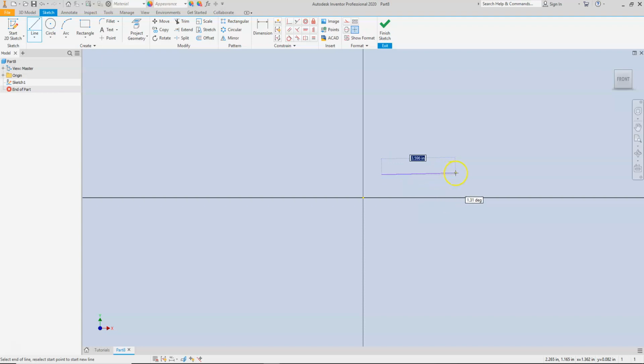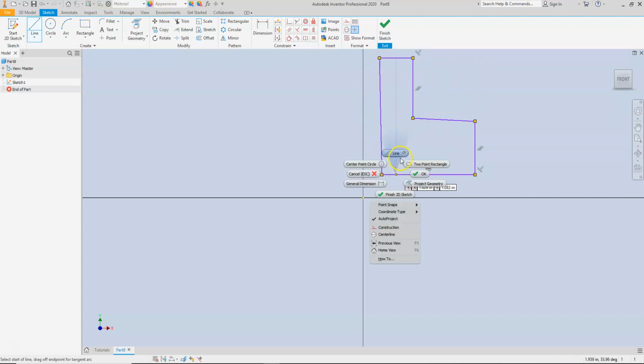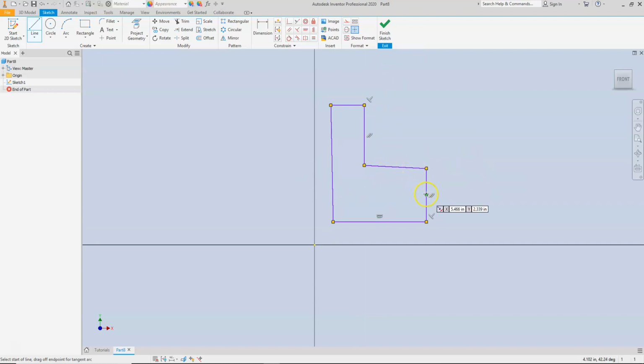So for this problem, I'm just going to ask you to basically sketch the overall geometry. I missed that, but oh well, it's okay. We're just creating a sketch, and I'm not assigning any dimensions, and at this point I haven't assigned any of the geometric constraints that need to go with this problem. Geometric constraints, for those of you who are crossover from AutoCAD, are things like your endpoints and keeping things perpendicular, parallel.